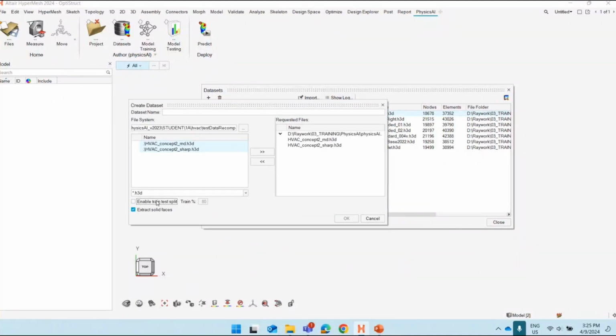When you enable train test split, the files chosen for training and the files chosen for testing are random. So you will not be able to specify that the first 10 are used for training and the last 2 for testing. It's going to be random. Now this will be the test data. Same thing, just hit OK, and now read the testing data set.